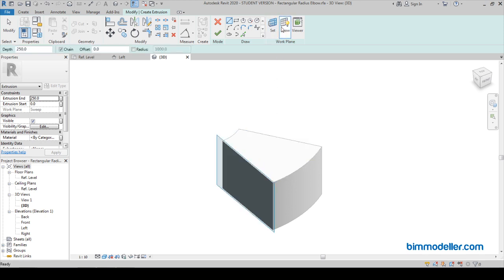Show, yes, I have selected the front face. Pick line and lock the line. I'm using Tab to select the continuous edges like this, and I'm going to give an offset of 15, and click one more time on the outer side.